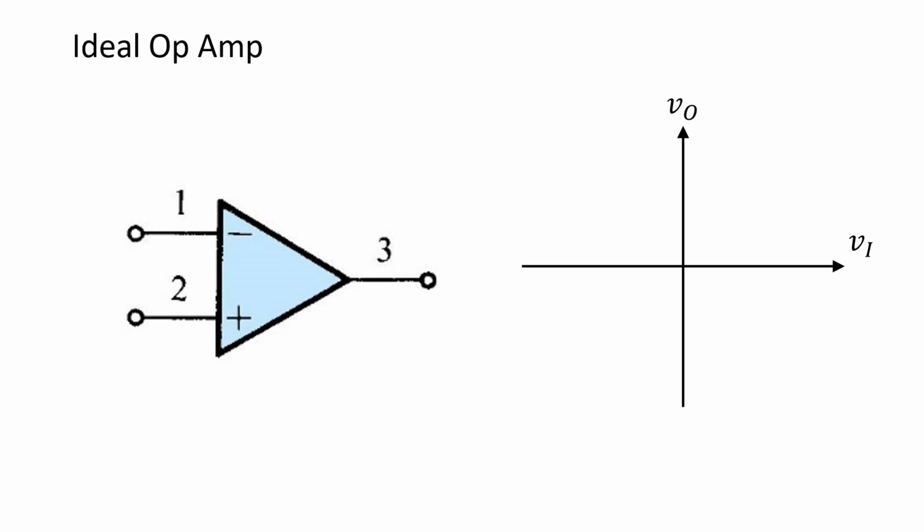If we consider the output of an op-amp in response to a DC input voltage Vi, we would expect that at zero input voltage, we would have zero output voltage. Moreover, we expect that with small input voltages applied, we would see a large gain at the output. And of course, for large enough output voltages, we know that the op-amp output would saturate. Strictly speaking, this isn't an ideal op-amp, since an ideal op-amp would have infinite gain and no saturation, but this is certainly an op-amp without the DC imperfections that we're going to talk about next.